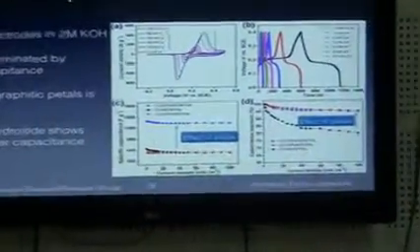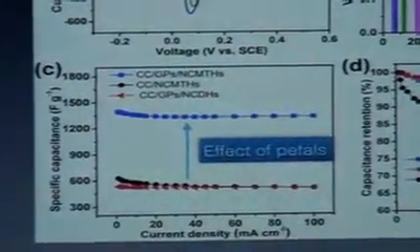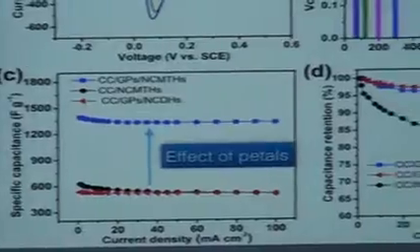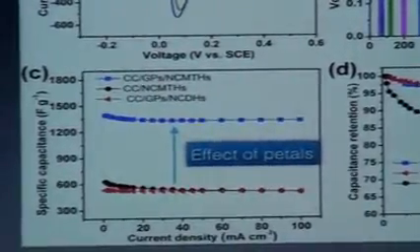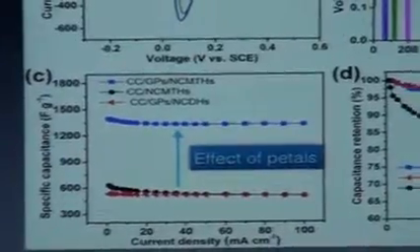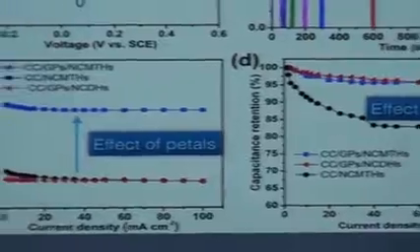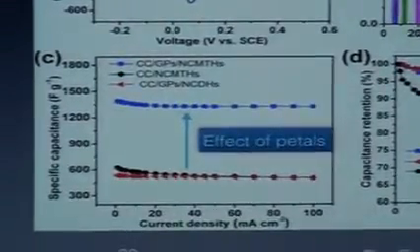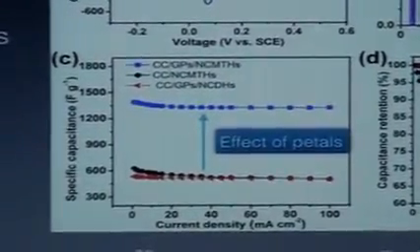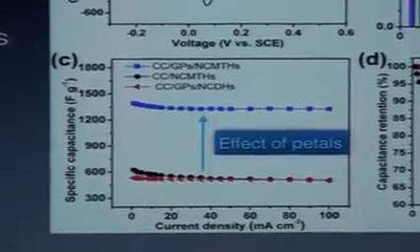We also have down here a specific capacitance for different current densities. So as I said before, if you start to charge or discharge your device faster, it will potentially be manifested as a reduction in your capacitance, right? We don't see very much of that, only at these very, very low densities, but this was nice to see. It's a very, very high level of specific capacitance, and we can do different experiments.